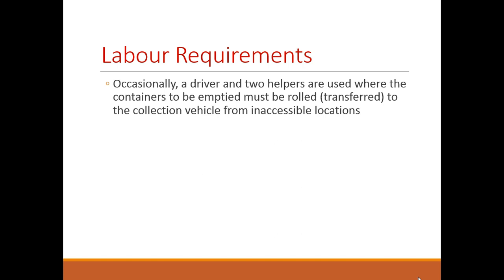Now occasionally a driver and two helpers may be used where the containers to be emptied must be rolled, if it's very large, to the collection vehicle, particularly where your storage area appears to be in inaccessible locations. For example, it may be in an alley. Remember, the vehicle would not be able to drive down the alley because it's much too narrow, or inside little gaps or lanes. We have a lot of these kinds of layouts and topography around Trinidad, so you would often be faced with this kind of scenario.